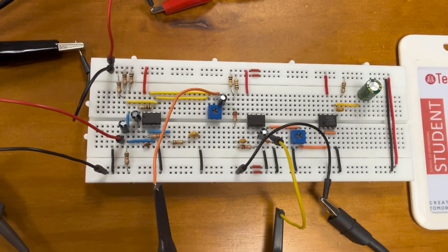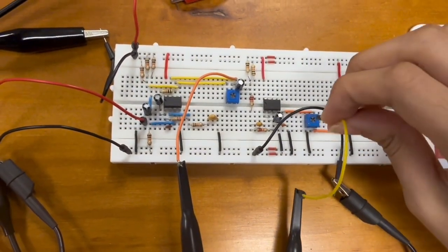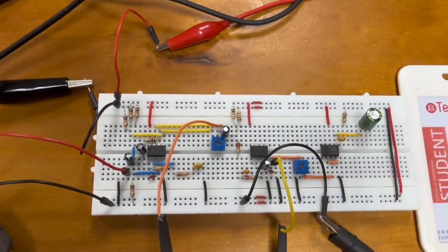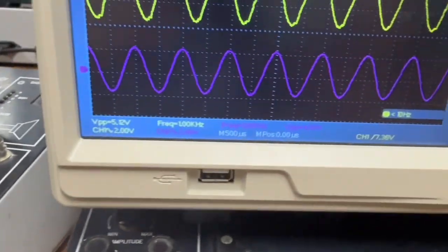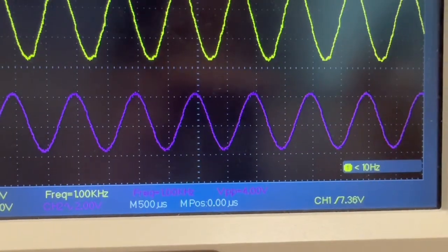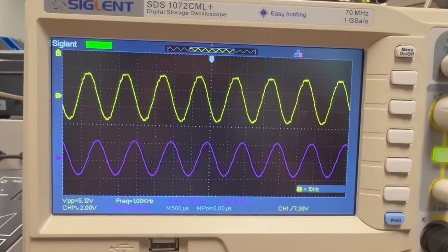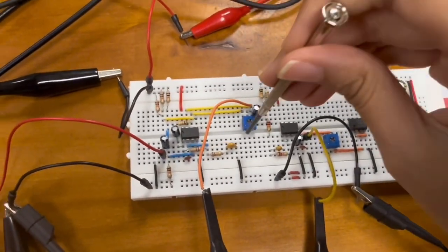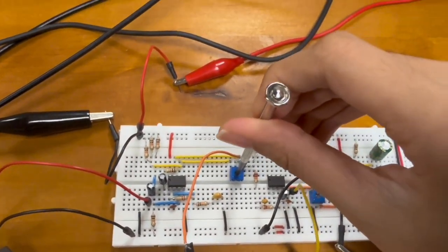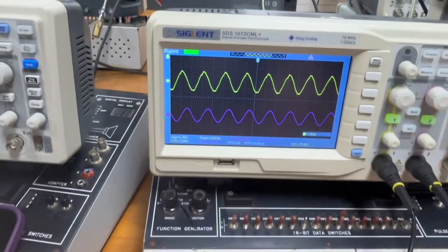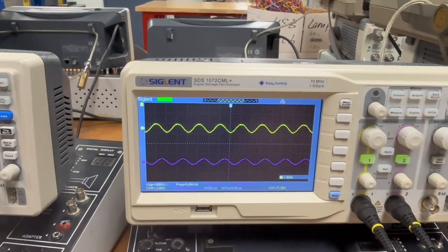By keeping TP3 at channel 1 and all else untouched, we can place the channel 2 probe of the oscilloscope to TP4, and there we get a filter output voltage of 4 volt. The output waveform at TP4 will be determined by the output at TP3. Hence, by adjusting the trimmer at stage 2, we can control the output at TP4.